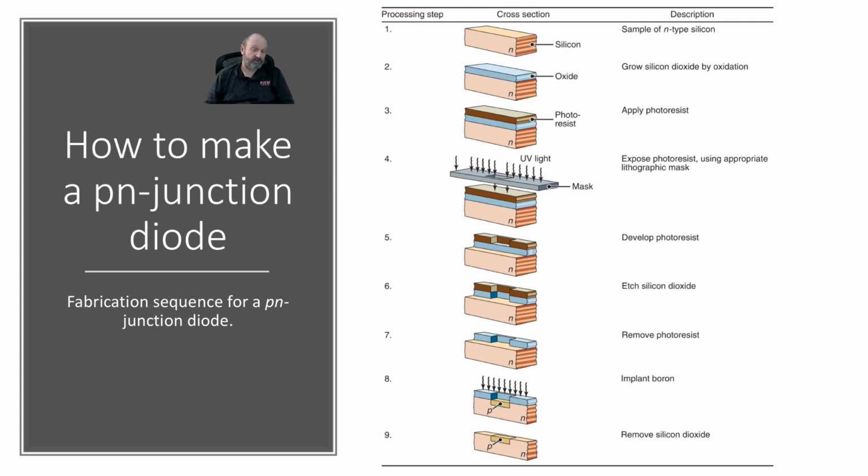And the lighter molecules tend to be smaller. So smaller molecules can go through oxide much easier than big molecules. And they're also moving much faster, so they have a better probability of getting through the oxide layer and actually forming on the surface. So you've got some homework that talks about oxidation growth, and they have some oxidation curves for wet and dry oxidation. And that's the difference. The wet oxidation is with water vapor. The dry oxidation is with just O2, regular oxygen gas.